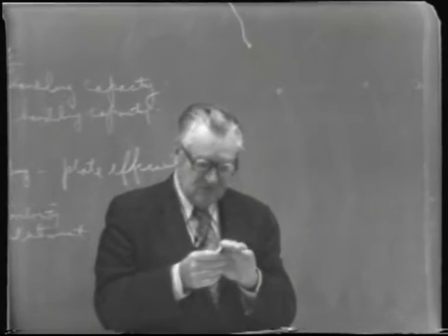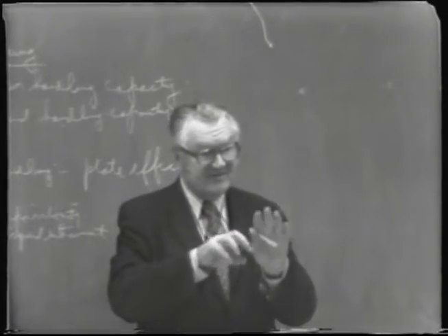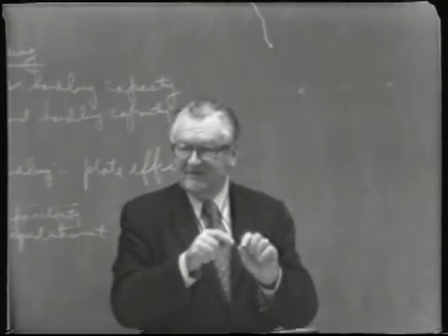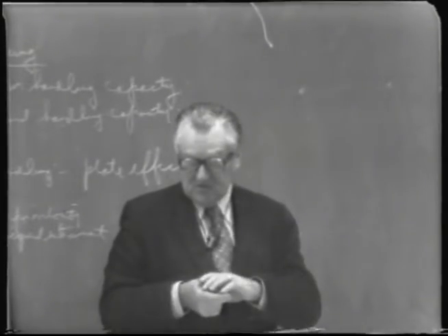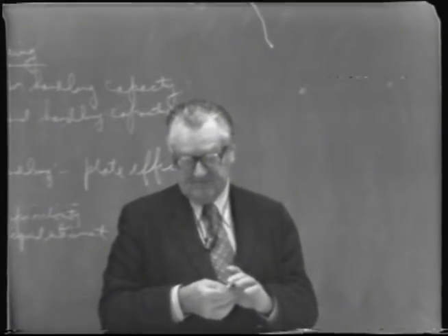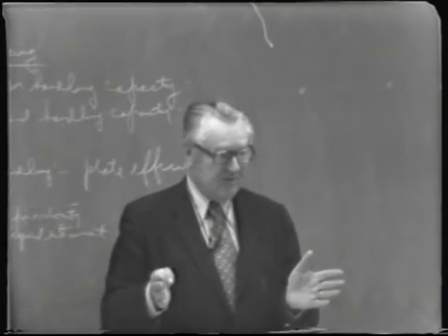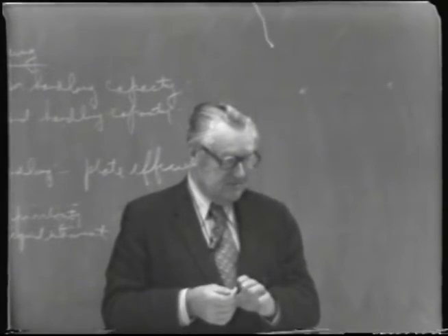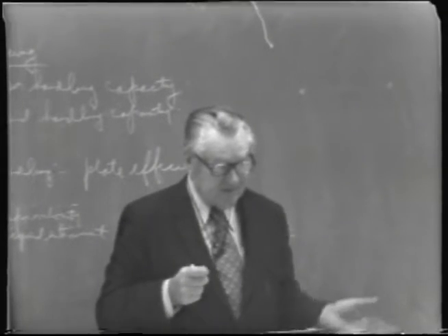If you have too low a vapor velocity, you may have no entrainment, but you don't have very much action on the tray, you don't have complete interaction of the bubbling with the liquid, and you'll also get low tray efficiency. So there is a region, maybe a fairly wide range, in which you get better efficiency at higher rates or lower rates. Vapor rates I'm talking about.